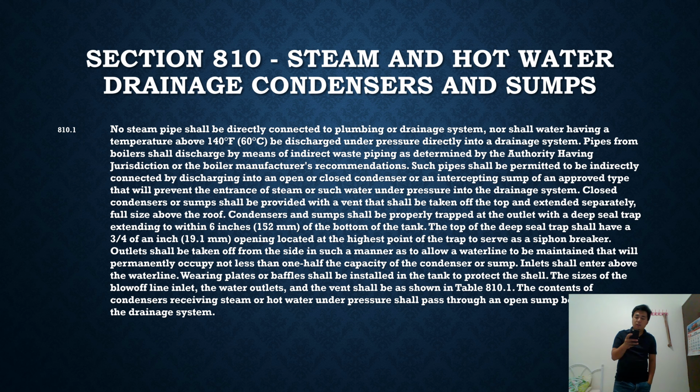The condensing should be achieved with a minimum of undercooling, reduction of condensate temperature below the steam temperature. The condenser is also arranged so that gases and vapors from the condensing steam are removed.